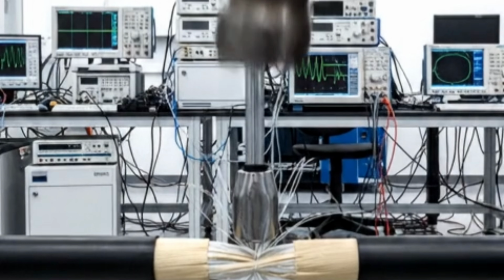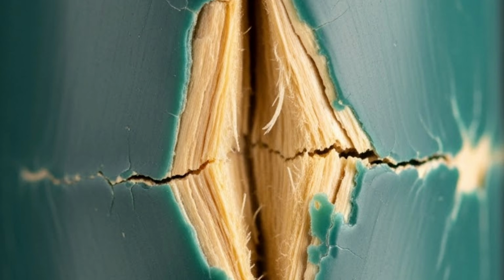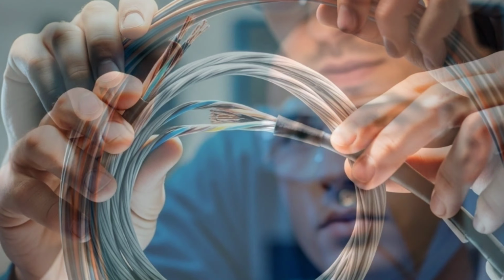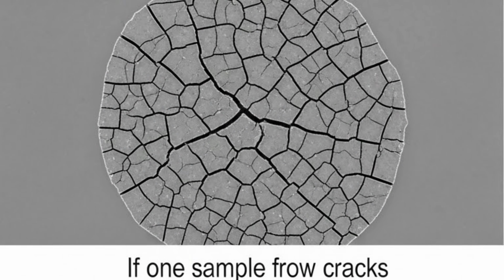Examination after test. After the impact test, the insulation or sheath is examined visually. No magnification is used. If no cracks are observed, the sample passes the test.